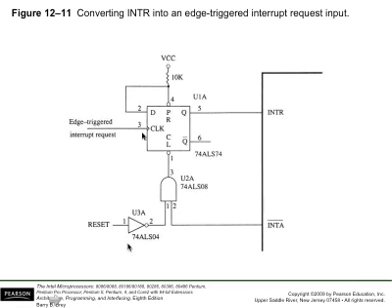In the bottom part, we have a reset, and then we have this INTA. Reset serves as a control to clear this D flip-flop. So at the very beginning, when the system resets, this is going to be a 1, so I have a 0 after this AND gate to clear the D flip-flop.